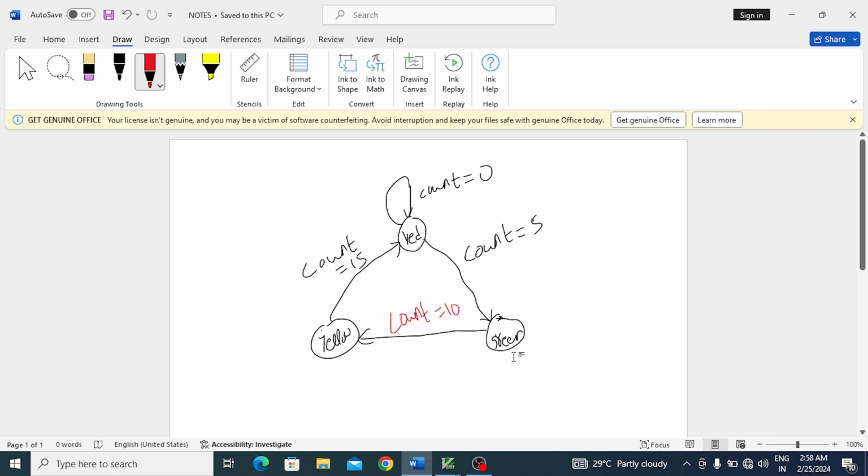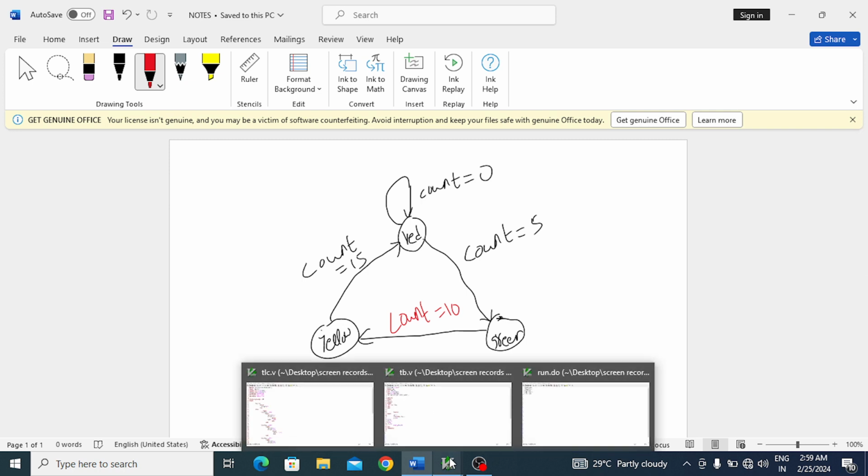Why did I take this order of states? Generally in a traffic light controller, after red we get green, then we get a yellow indication, which indicates it is going to get a red state. So accordingly I took it. Now we'll see the design code, then we'll do the verification code also, run the code and analyze the simulated output.